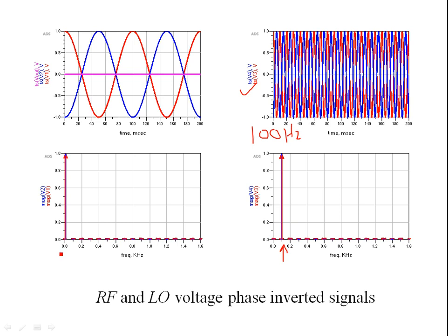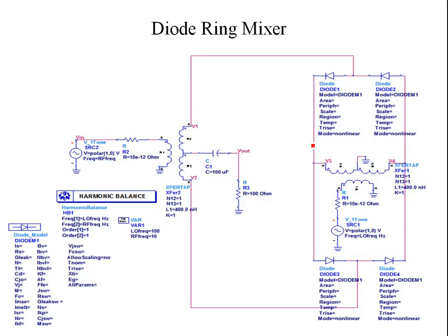Similarly, this is a low frequency. This is at 0.01 kilohertz or 10 hertz. This is a 10 hertz signal, and this is a 100 hertz signal. So you see over here you have one cycle. This is 100 milliseconds, 0.1, so 0.1 versus 10. So similarly in 100 milliseconds you will have 10 cycles. This is 100 hertz.